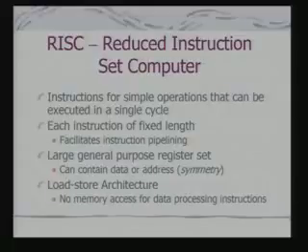A fixed length instruction facilitates what we call instruction pipelining, because I know that if I am fetching an instruction of a fixed word, the next byte or word that I fetch would correspond to the next instruction, and it will not correspond to a byte or word of a previous instruction. So I can design fetch cycles to fetch words of fixed length which correspond to a single instruction